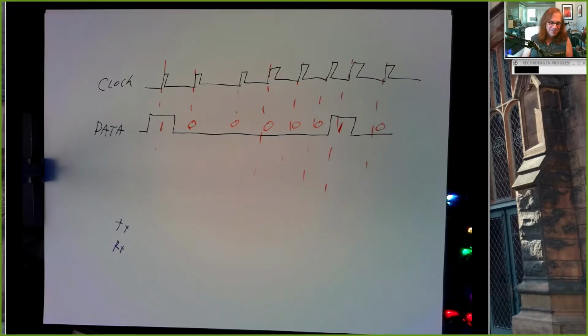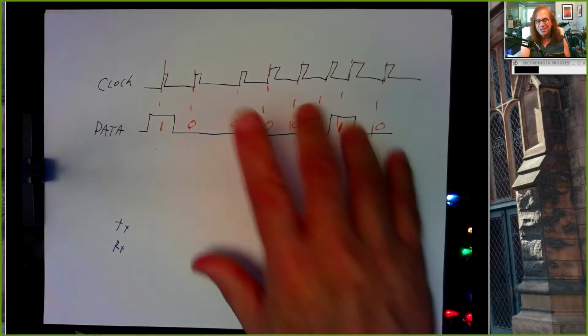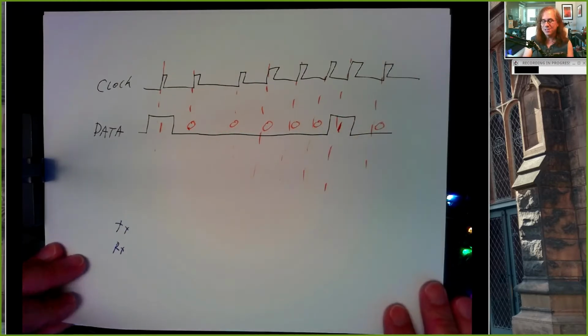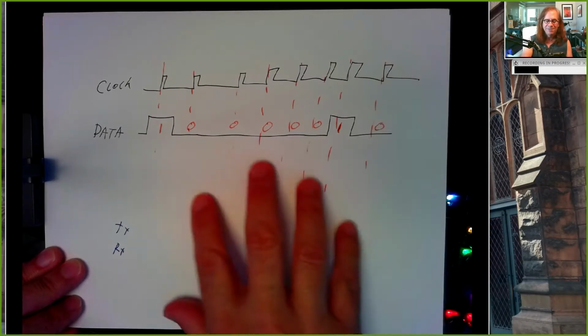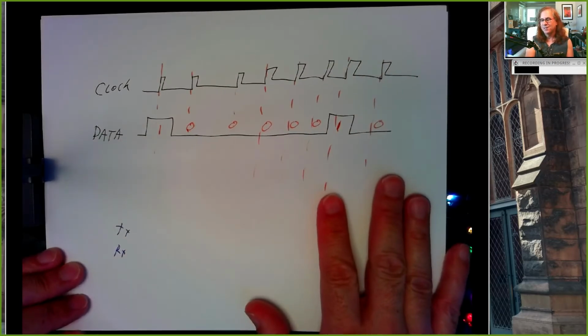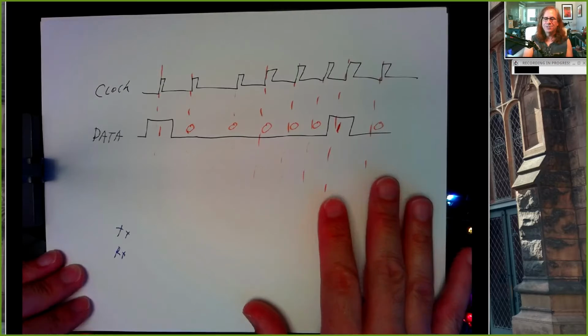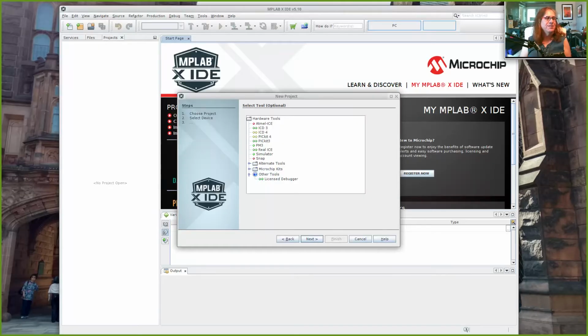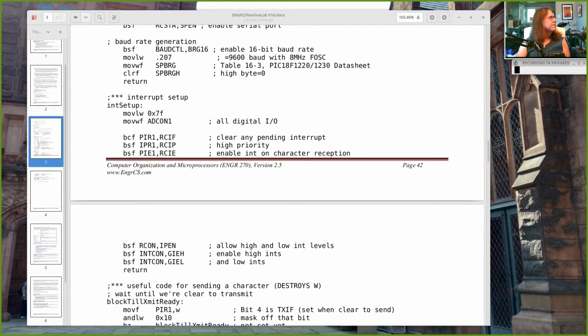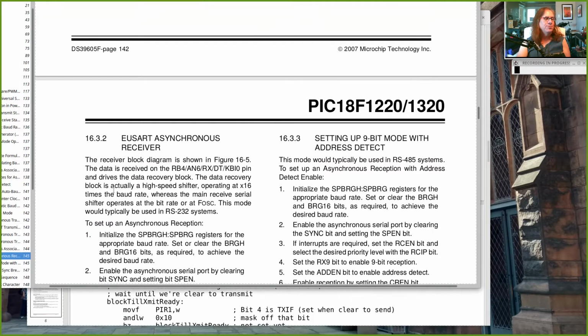There's a lot of support for this style of communication, so there's libraries and such. But when you're down at the assembly language level, interfacing with pins on a microcontroller that directly relate to special function registers, you can kind of do what you want. And we don't really have to do any of this fancy stuff using the whole UART subsystem.